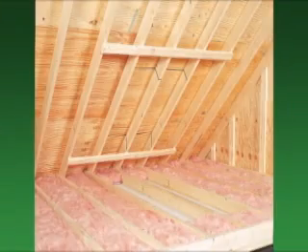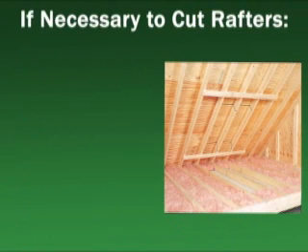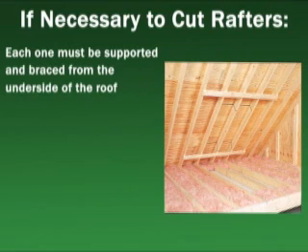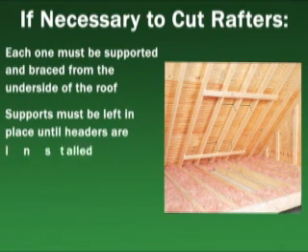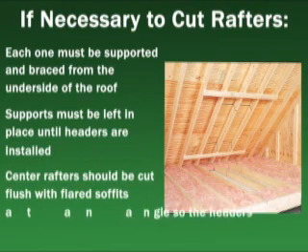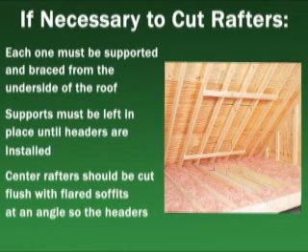Now, cutting the roof rafters. If it's necessary to cut the rafters, each one must be supported and braced from the underside of the roof. The supports must be left in place until headers are installed. The center rafters should be cut at an angle, so the headers will be flush with the flared soffits.